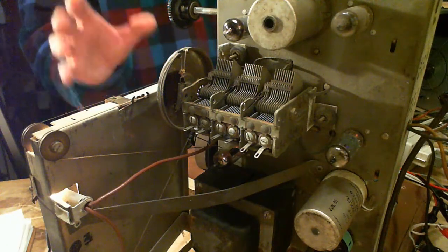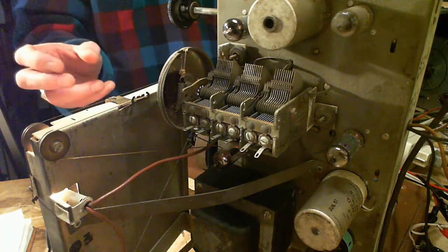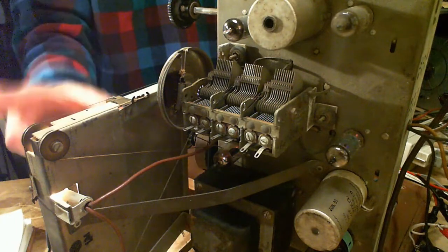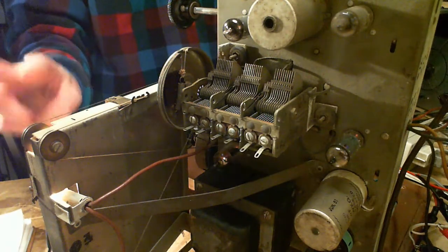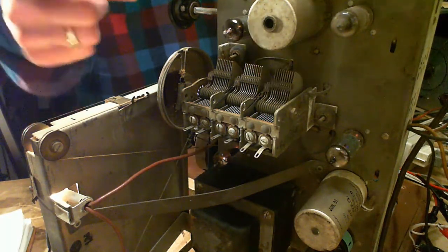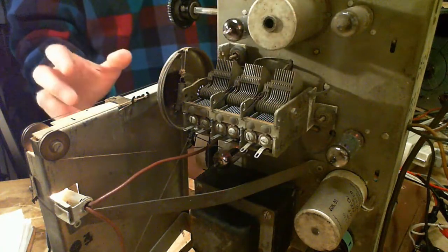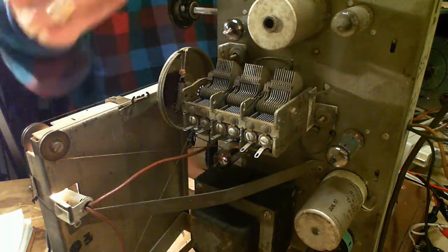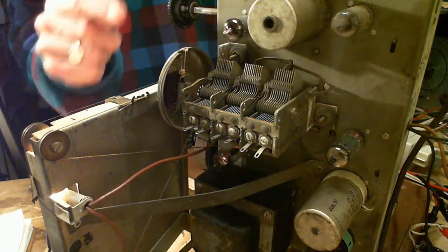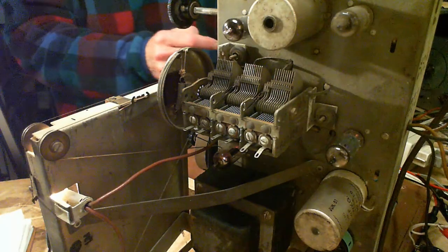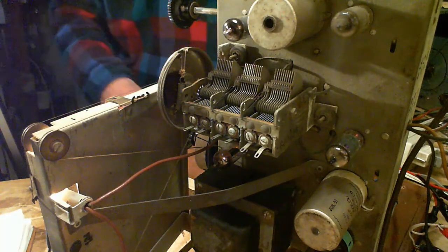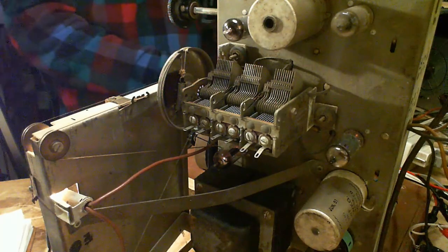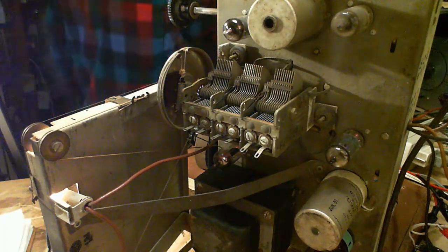So it's kind of like two radios in one here, where they have a radio with a large range. That'd be the broadcast band and the shortwave band. And it relies on the big capacitor. And then when you go to these band spread, the big capacitor plate's gone and just the little plate's operating. It's not really like another whole radio, but kind of. That's not common.